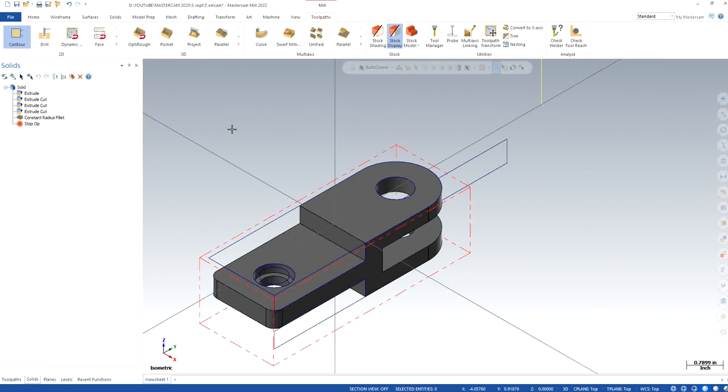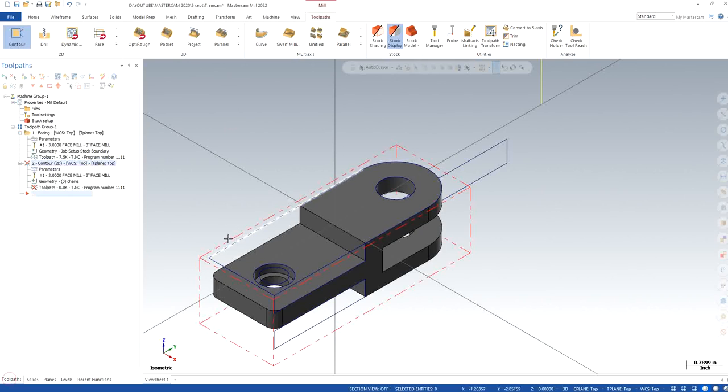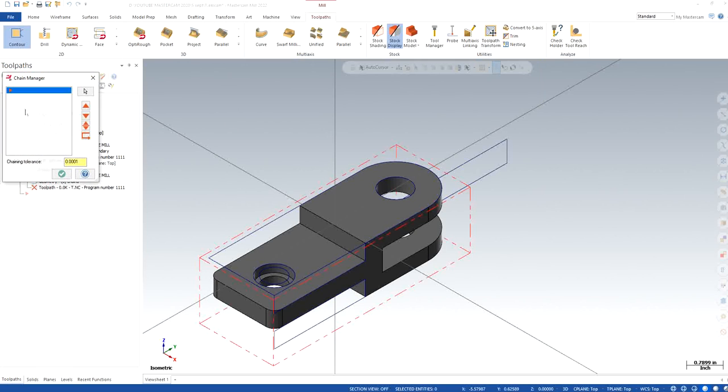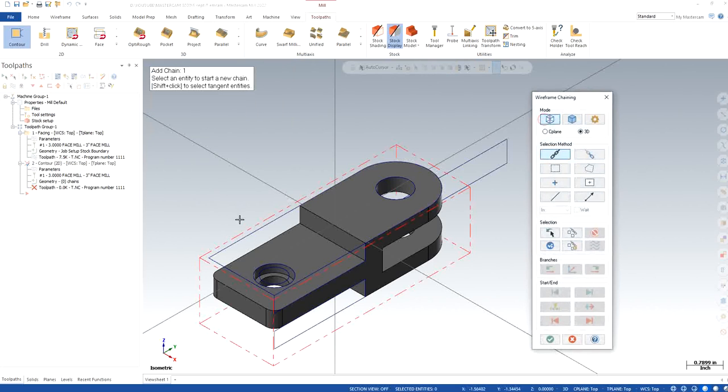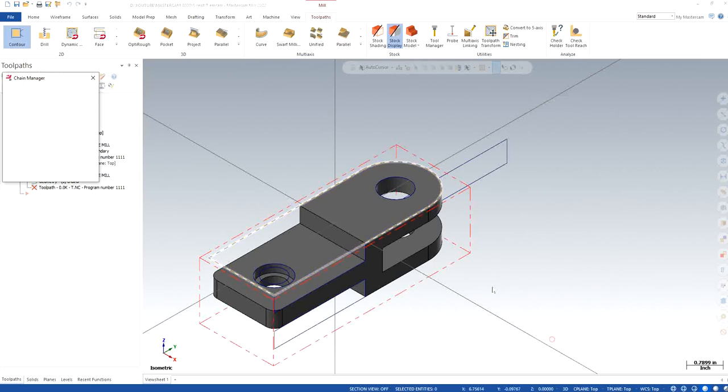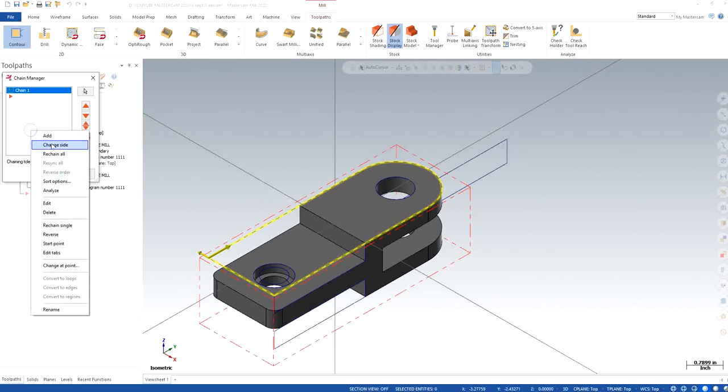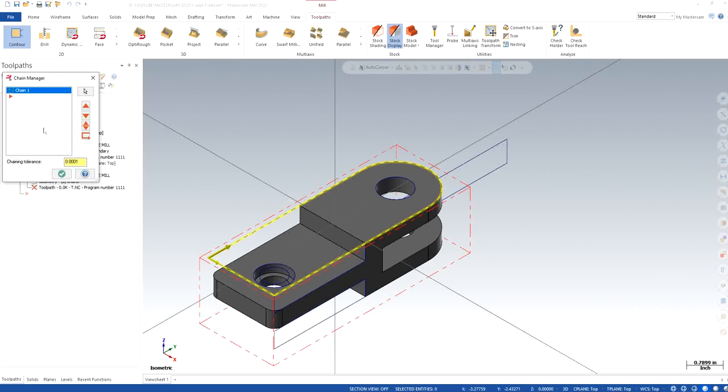Regenerate a little bit, not an issue. So the wireframe, I can just simply use it and click on geometry and add the wireframe right here. There we go. This as well, and click OK. The arrow is outwards. I want the arrow to be inwards, chain side, and also the direction is going to be reverse. There we go.